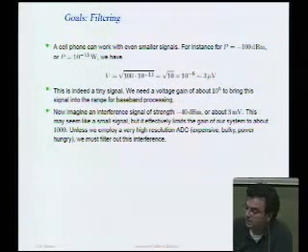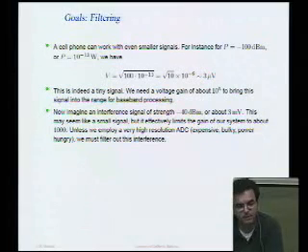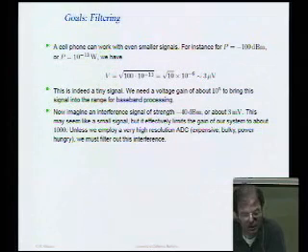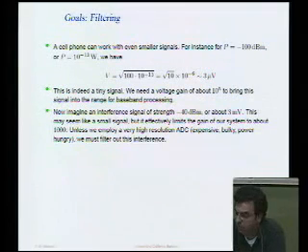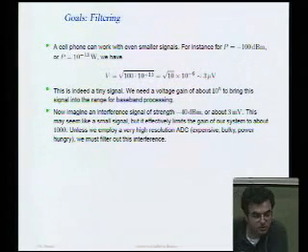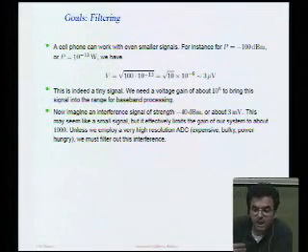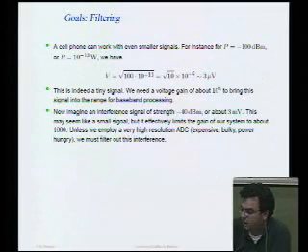And to gain some intuition about how small that is, go in the lab and look on an oscilloscope. Start out with, let's say, 100 millivolts, and then keep making the voltage smaller and smaller. And as you get into the microvolt range, you'll see that it's all blurred out, it's all noisy. That's because of the finite dynamic range of that oscilloscope. And it's also because of the noise that's present with that signal. That noise, as we'll learn about in this class, is proportional to the bandwidth of your observation. And the more data you push through a link, the more bandwidth you need, and therefore the more noise that will enter your system. Okay.